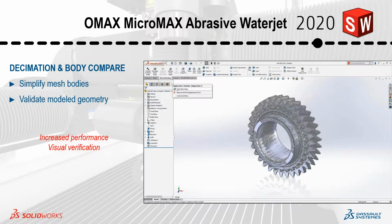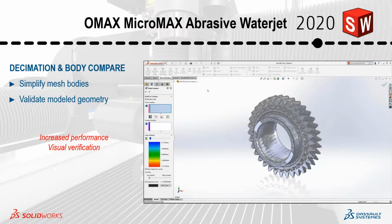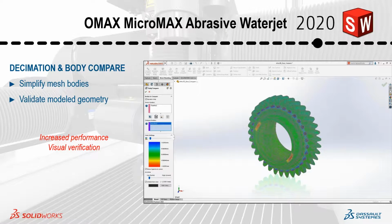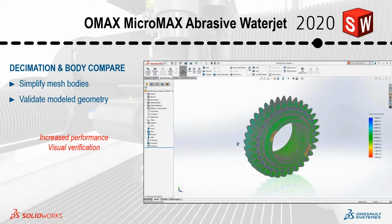Once done, you can compare the completed part with the initial reference mesh data. You can see those are vertices of the original mesh and solid body. With this, we can clearly see where the design is flawed or where the dimension is incorrect. So we can make those changes, as you can see from the color bond in this section right here on the right, the body compare legend. We're actually comparing the mesh, the scan data, and the solid body that we created in SolidWorks.